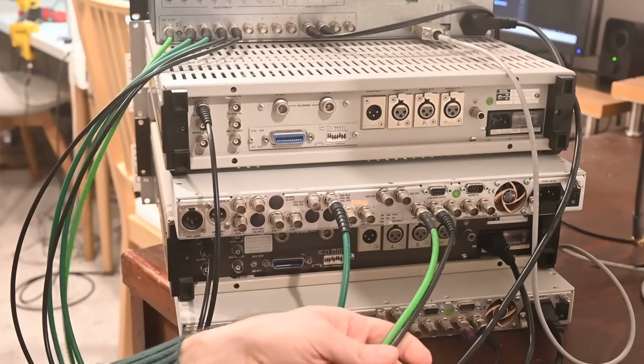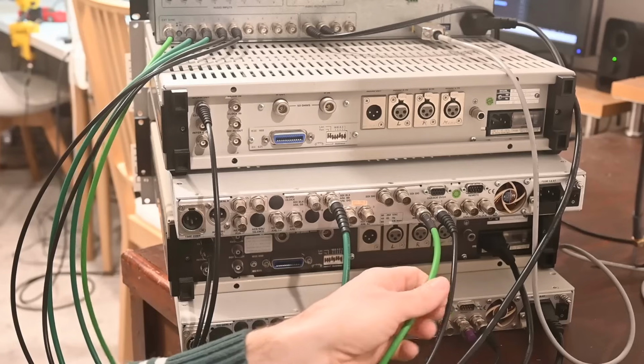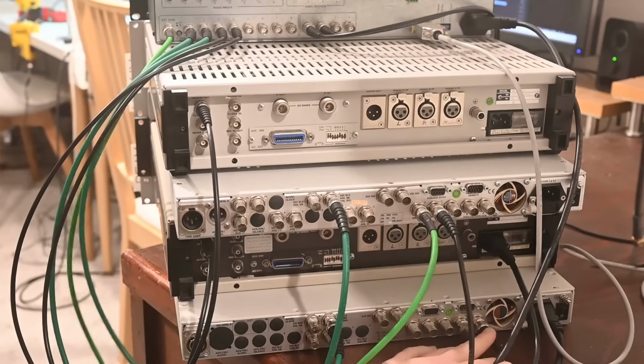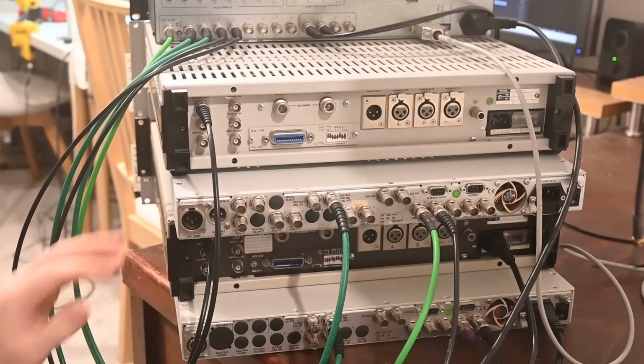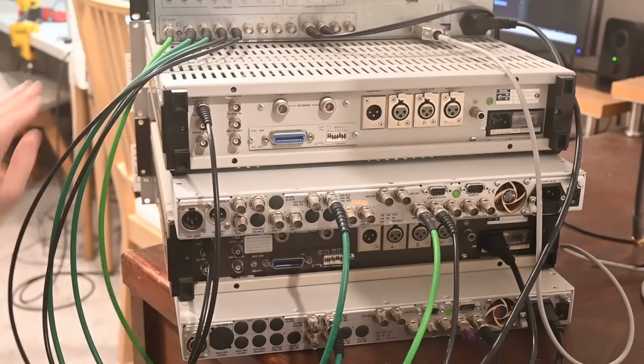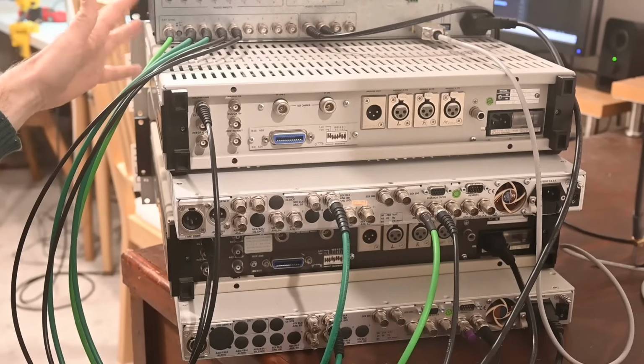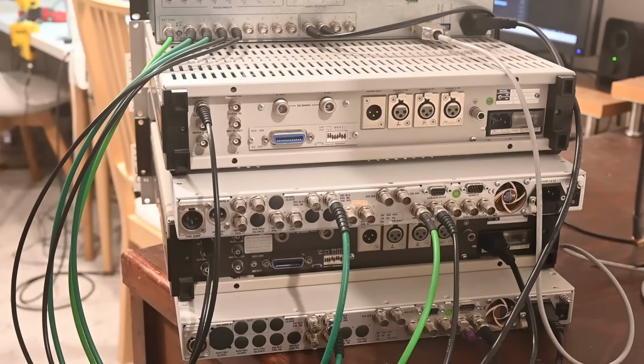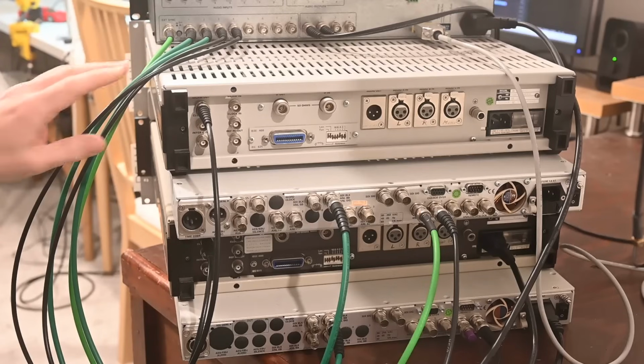The master sync generator has two black and burst outputs. One of them is going down to the slave down there. So this one is genlocked to this unit. The second one is going up to the matrix switcher, and because this is a synchronized switch, we ideally do want to be switching in the blanking periods if we can.